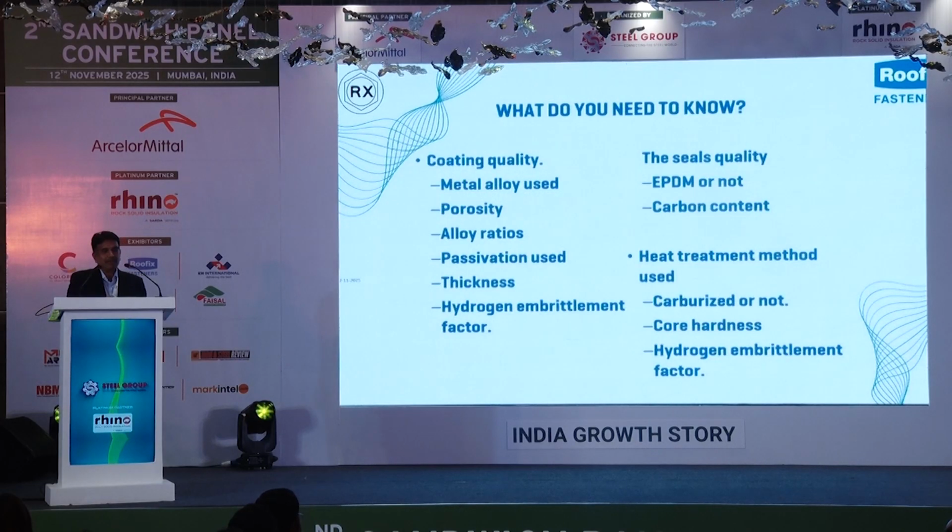Most of the time while selecting a fastener, you need to know the porosity of the fastener, the metal alloy being used, the passivation, the thickness, the hydrogen embrittlement factor, the seals that are being used in your washers, and the heat treatment undergone by the fastener that you have bought.